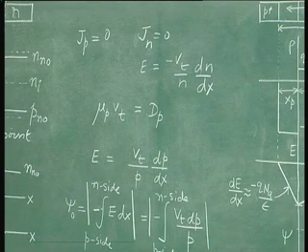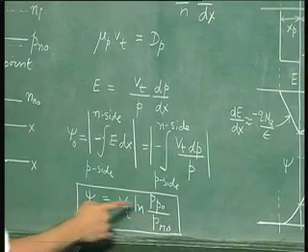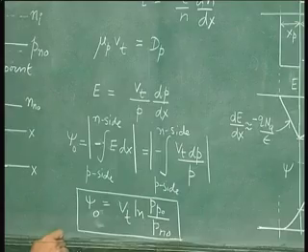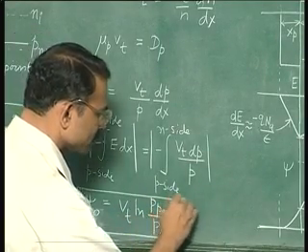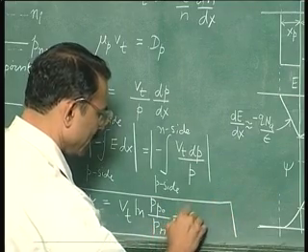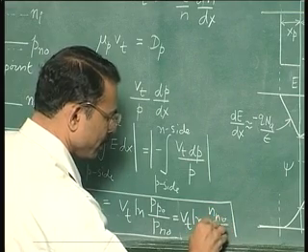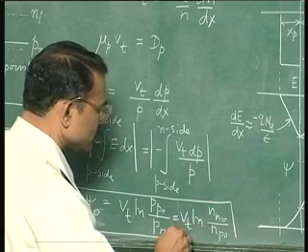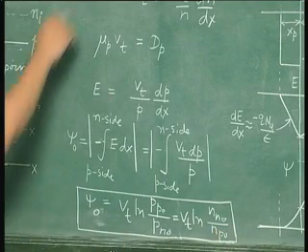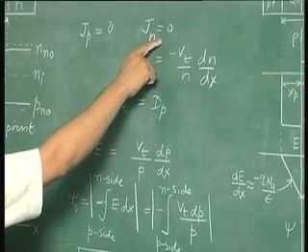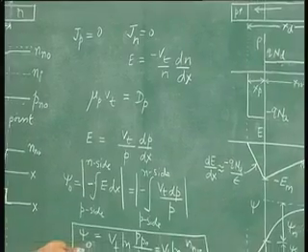So that being the case, you have not just one equation for built-in potential. You could calculate the built-in potential either from the hole concentrations, or you could calculate also from the electron concentrations. So I can write the same thing also as Vt ln n0 by np0. So Jp equal to 0, Jn equal to 0 has given us the built-in potential of the PN junction.